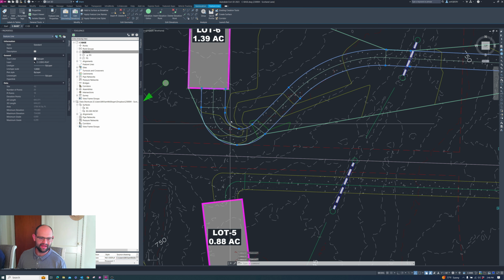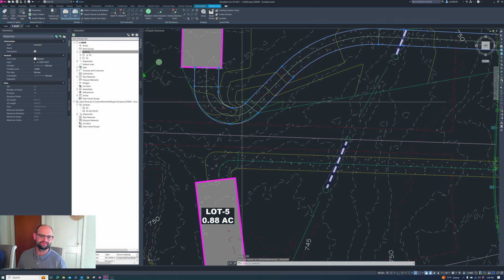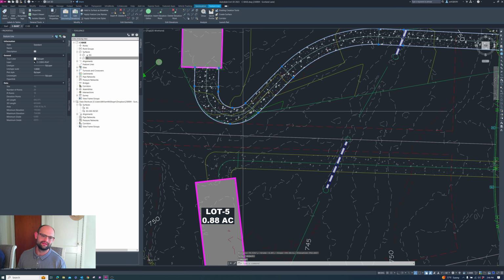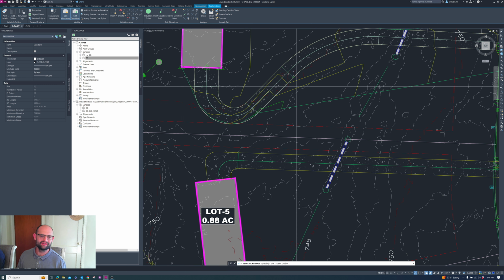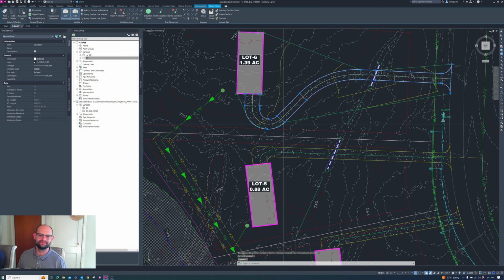It's like something funky happened over here. Let's see what we messed up. Ooh, 29. That's not right, is it? Let's reset the smooth slope between here and here, and rebuild the surface by right-clicking in the tool space. That's a little better, but the other side's messed up too. So select, select, good. Same thing for the center line. Now I think that got us. Let's rebuild. Much better.